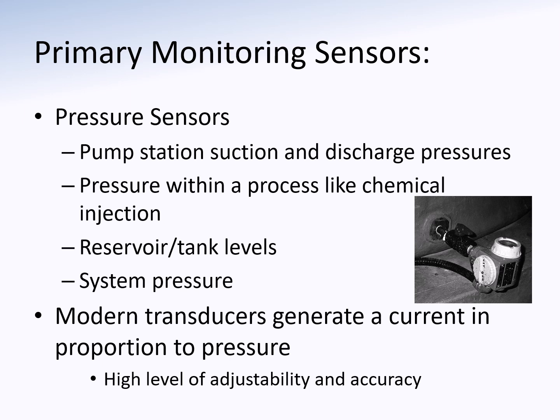You've got pressure sensors, and those will be installed at pump stations, reservoirs, maybe just random locations throughout your distribution system, chemical injection systems, and then you've got the transducer that will take that pressure, kind of like that thermistor we discussed when we were talking about pumps and motors, and it will generate the current and be able to show you what that pressure is, which I think we're going to discuss here in just a sec.